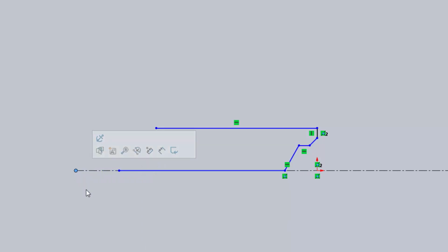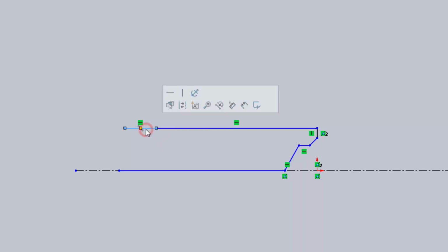Oh, okay. That point is just the end point of the center line. If I had a point like that that looked like this, I'm going to hit escape to get out of there. See these two lines that are solid? You almost never want to do that. This little point can cause some problems. It's better to have one solid straight line than two shorter lines.